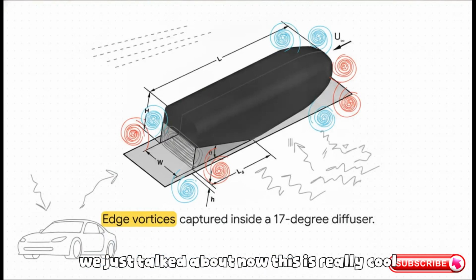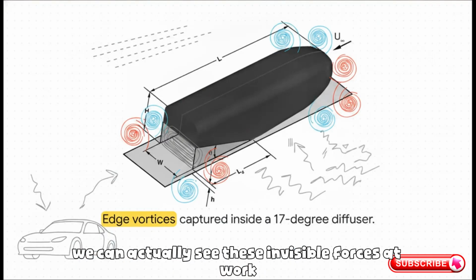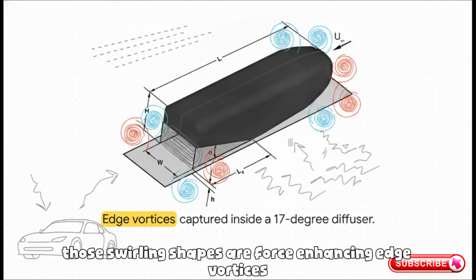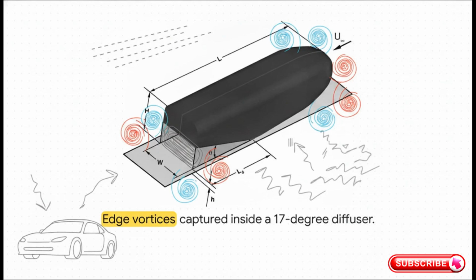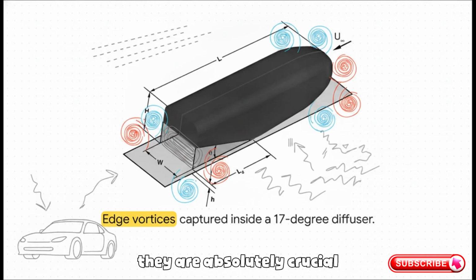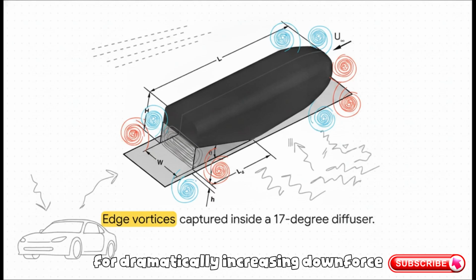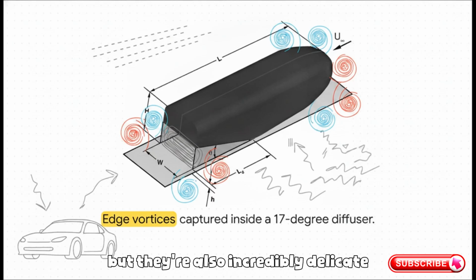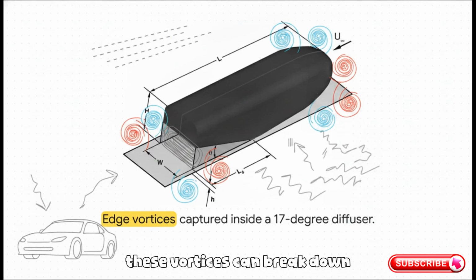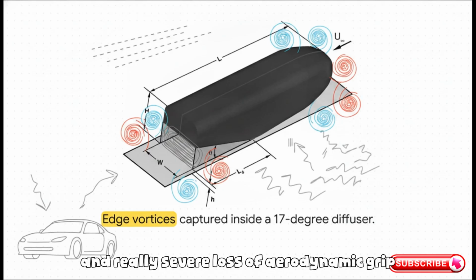Now this is really cool. We can actually see these invisible forces at work inside the diffuser here. Those swirling shapes are force-enhancing edge vortices. They're basically highly concentrated spinning tornadoes of air that form right off the edges of the diffuser plates. They are absolutely crucial for dramatically increasing downforce, but they're also incredibly delicate. If the car gets even slightly too low to the ground, these vortices can break down, causing a sudden and really severe loss of aerodynamic grip.